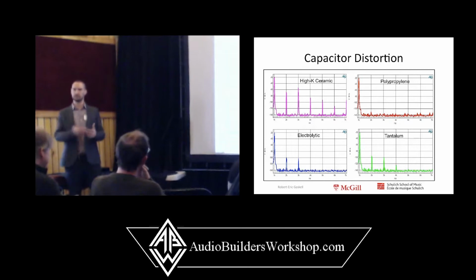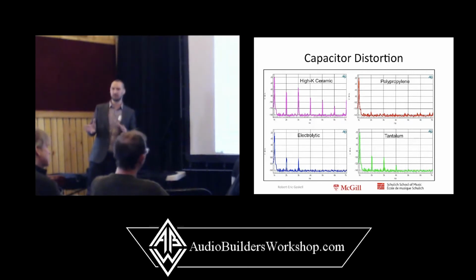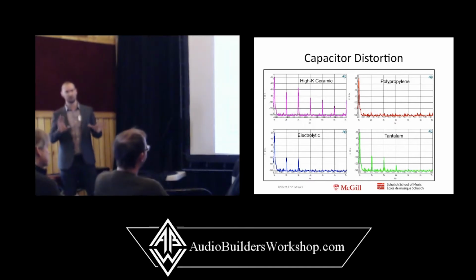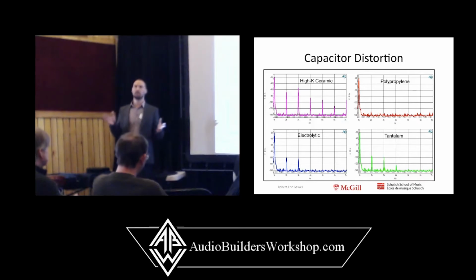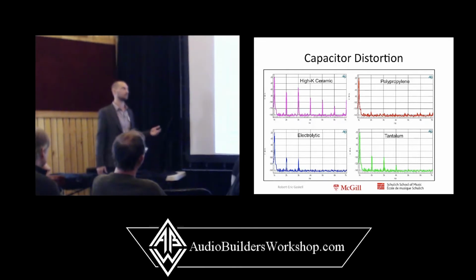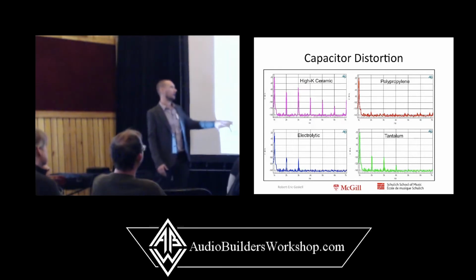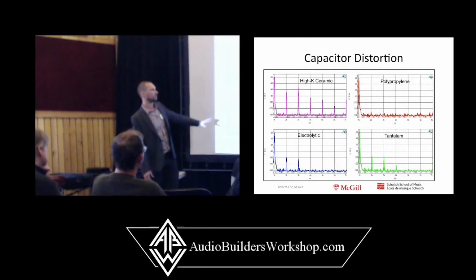where electrolytic will be small and much, much cheaper. So your choice in capacitors will make a difference in the sound, and how perceivable that difference is is up for some debate. Typically, we're using these capacitors at the low end, and the ear is much less sensitive to distortion at low frequency than it is at high frequency.